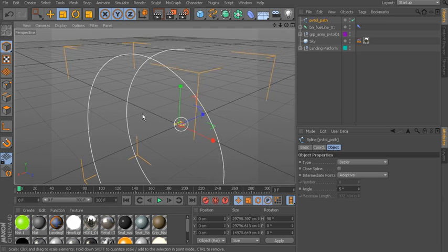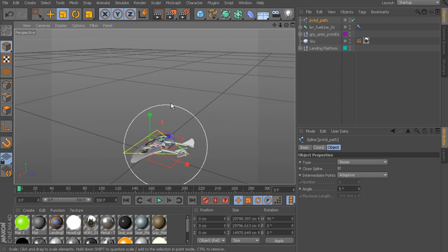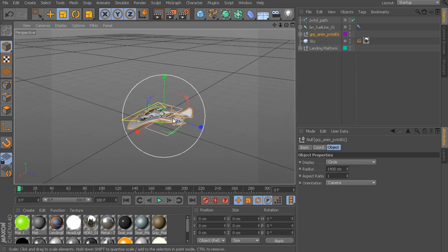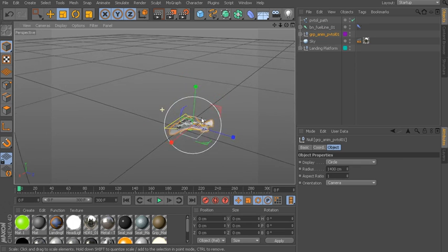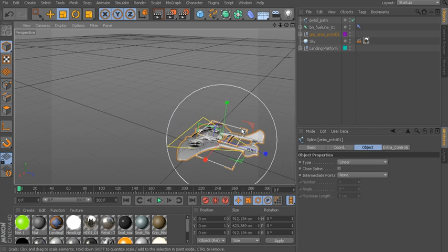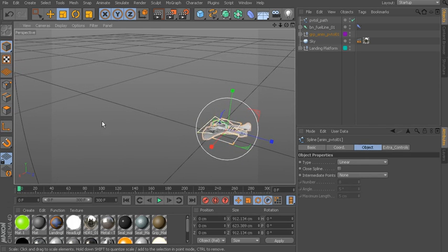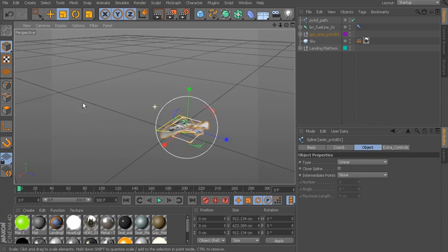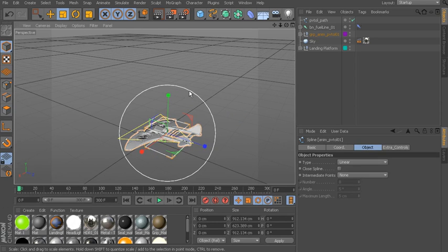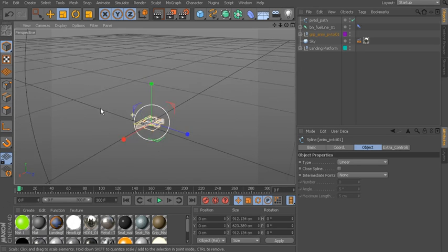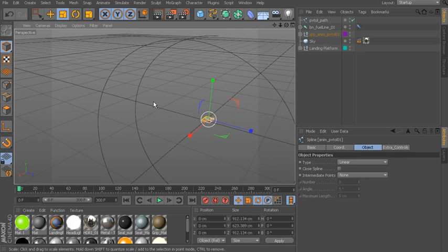Alright, so now it's time to connect our object. Now let's be smart about this. We don't want to connect our animation control. Instead, let's go ahead and connect our group. The reason why is, what that means is that our group is going to be tied to our path while we can animate any offsets we'd like on our animation control. Chances are we may want our object to veer off from the path just slightly in some way. So by connecting again the main group of our rig, and instead of the animation control, that gives us more freedom over how the object behaves along the path.